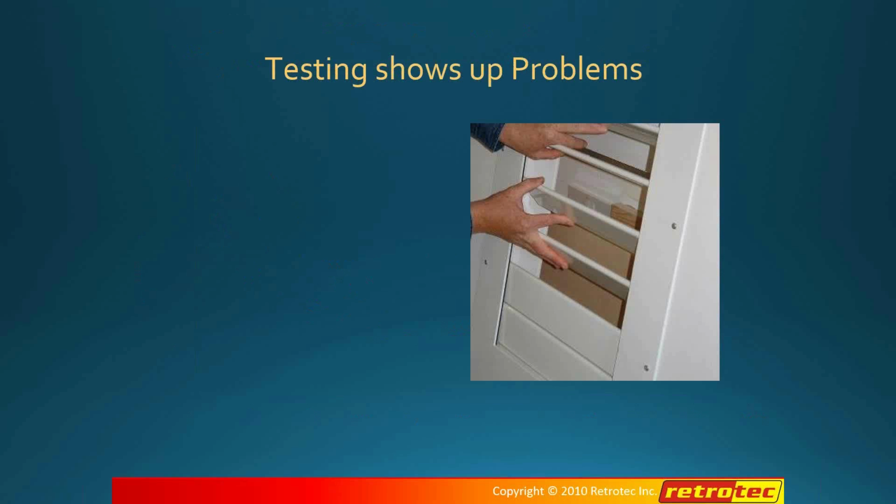Now, the other thing that we have determined is that it's not necessarily the solution to the problem to simply put in a vent. And we found a lot of problems with that. One problem was for a very big inert agent installer on the West Coast. They had 3 PRV, or pressure relief vent, failures. In one case, the manufacturer said it would open at a certain pressure, and it opened at 100 times that pressure. In another case, they were expecting a positive pressure, and what do you know, they got a negative pressure. And in other cases, the vents were blocked, or something along the relief vent path was blocked.